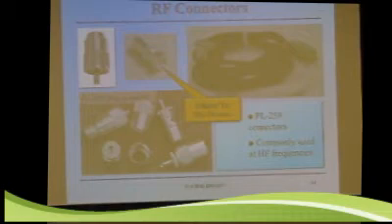In fact, more recently I got a crimper, and I wound up crimping them rather than soldering them in some cases. I've been experimenting with both of them. But you can put them on yourself, and if you do more of them, the better you'll get at it. The situation is most of us don't need to put that many on, 2 or 3 a year maximum, and so we never get that good at it. But you can put them on yourself and solder them. It takes a good soldering iron. You've got to have a good hefty soldering iron to do it because you've got to get those things pretty warm, but it is doable.